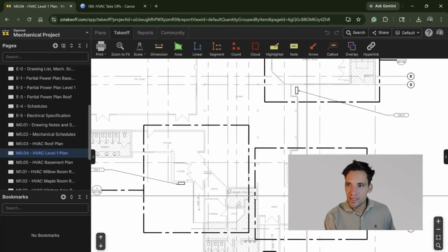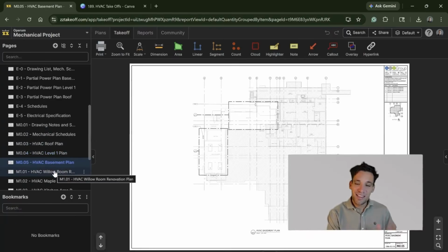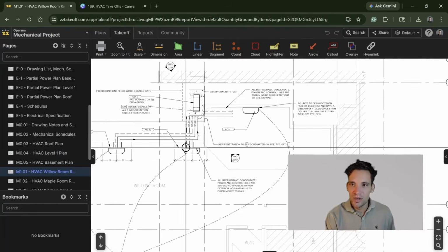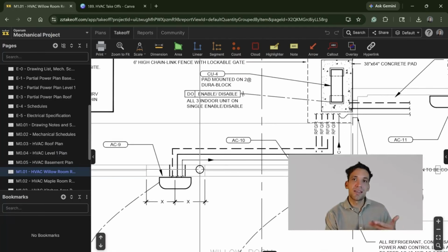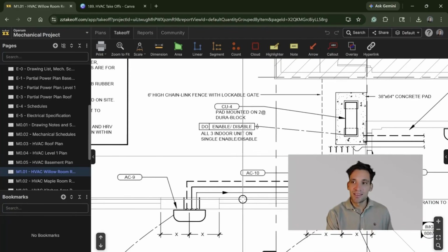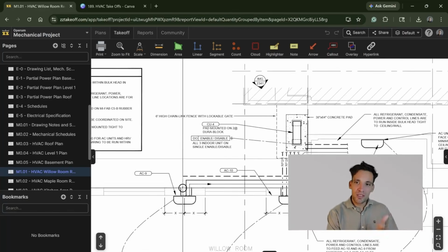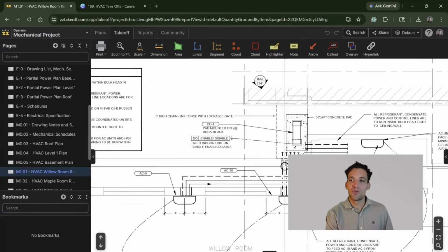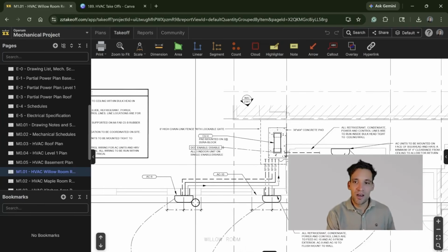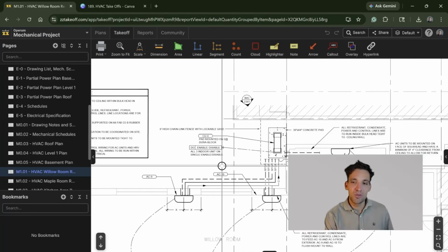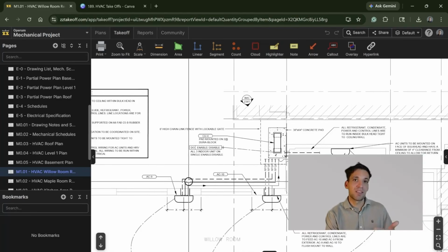Another thing worth noting is that, again, it depends a little bit on the purpose of the takeoff, but if we're talking about condensate pipe, which might be a couple of dollars a meter, this sort of minor consumable installation, I would not go and do linear measurements of all of these items. I would include that in the assembly for this specific AC unit.